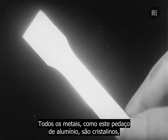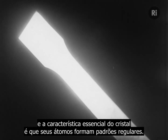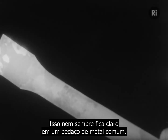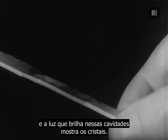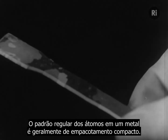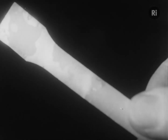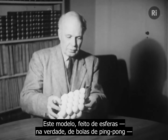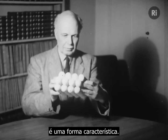All metals, like this piece of aluminium, are crystalline, the essential features of a crystal being that its atoms are in regular patterns. This is not always apparent in an ordinary piece of metal, but if we etch it with an acid, regular pits are formed, and the light glinting on these pits shows the crystals. The regular pattern of atoms in a metal is generally one of close packing. This model, made of spheres, actually of table tennis balls, is a characteristic form.